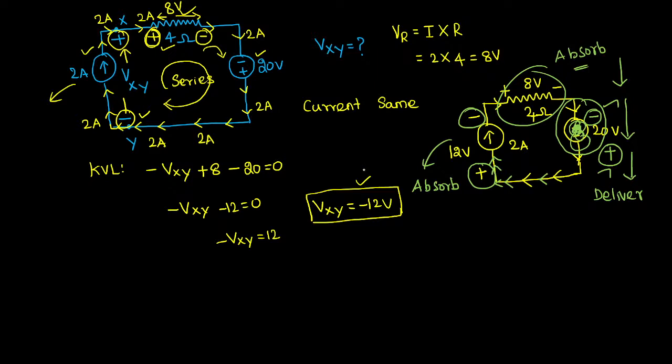You must analyze the circuit properly, identify the direction of current everywhere in the given circuit, identify the voltage polarity everywhere in the given circuit, then cross check the sources. After identifying the voltage source polarity and current direction, you can identify which elements are absorbing the power and which elements are delivering the power. That can be done only after completely analyzing the circuit, when you have more than one source in the circuit.